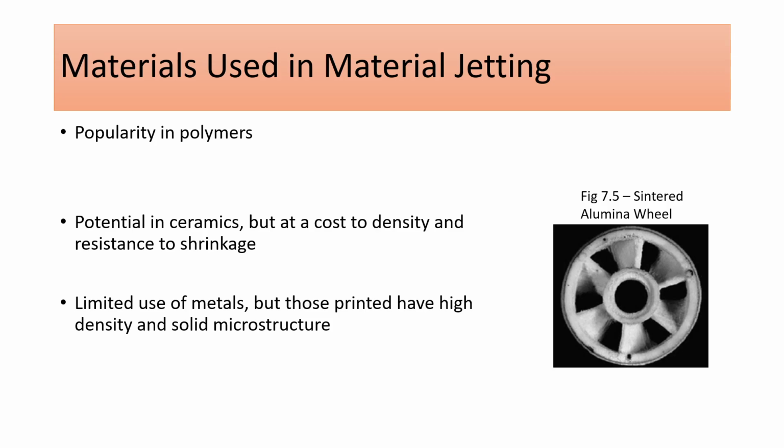Ceramics, when used, have shown some success in printing through the use of this liquid carrier with moderate viscosity. However, high concentrations of the suspended powder can make the viscosity too high to print. Also, the parts yield only partial ceramic density. Therefore, the green part will need to be burnt out and sintered, making it susceptible to shrinkage.